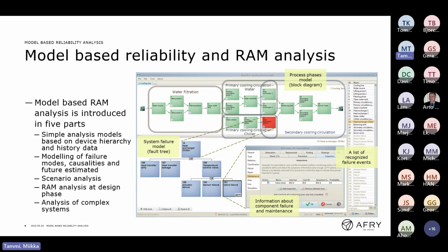First, simple analysis models based on device hierarchy and history data. Then modeling of failure modes, causalities, and future estimates. Then scenario analysis, and then RAM modeling and analysis at design phase shortly, and also RAM modeling and analysis of complex systems shortly. The first one is also called history data audit, and the first 3 together create the basis of our history-based scenario analysis approach.